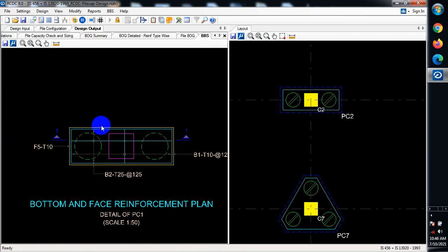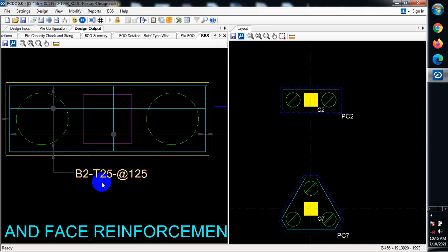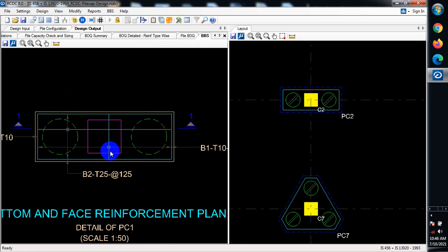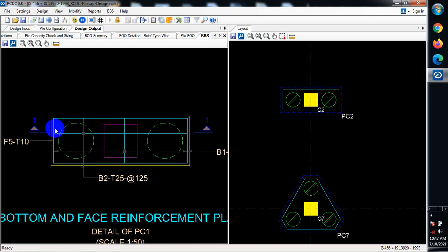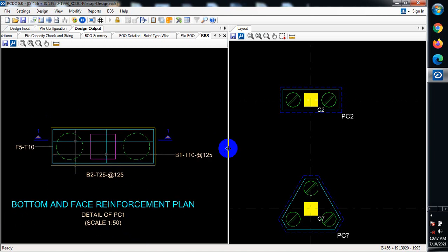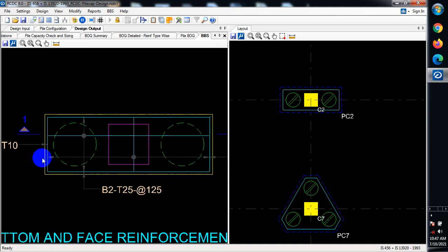While this one that spans along the longer span, along your L, this long bar here goes along your LX, this goes along your LY. I hope you understand that. Now you can see that this one that comes along this way, we have it at 25. Now if this is actually a normal slab, definitely this is one way. So the shorter span carries the main reinforcement, and then this one is more like the distribution bar. I hope you understand what is actually going on here.